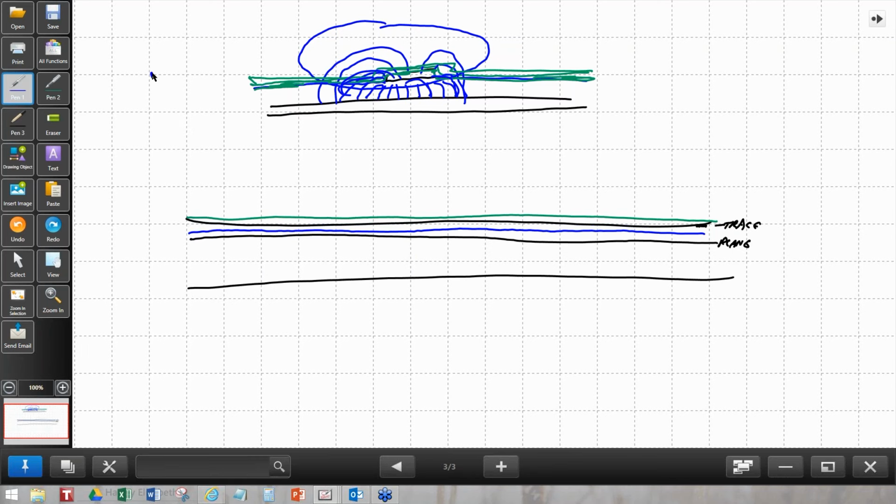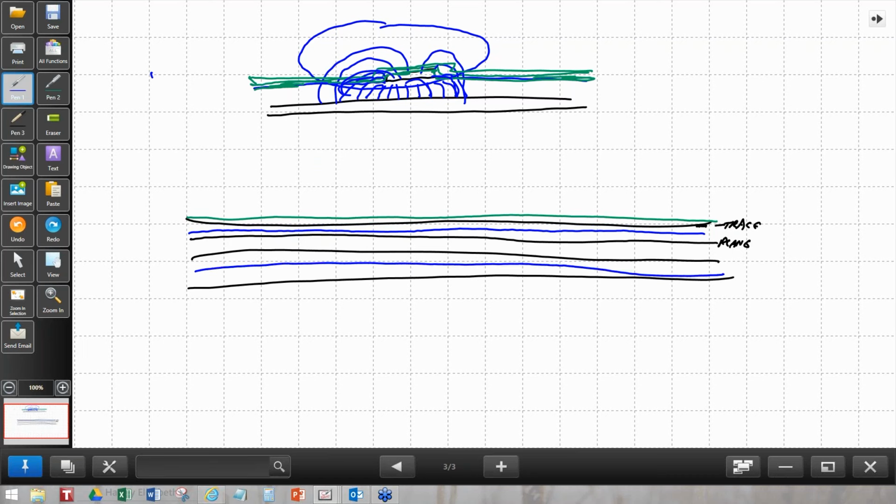However, if later on down inside the board between another set of planes, you do have, again, another signal trace, the field lines from this trace will pretty much be contained between those two planes. So the solder mask doesn't affect those. Just be apprised that if you're using solder mask on the top surface, you're going to have to take that into account in your characteristic impedances.